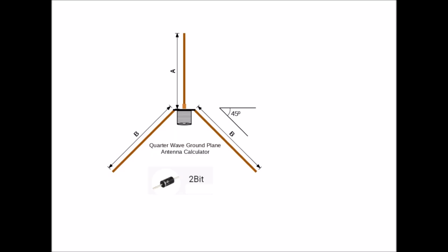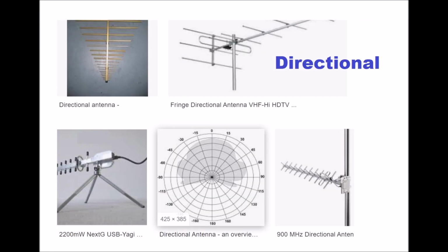Since monopole antennas rely on conductive surface, they may be mounted with a ground plane to approximate the effect of being mounted on the Earth's surface. More complex antennas increase the directivity of the antenna. Additional elements in the antenna structure, which need not be directly connected to the receiver or transmitter, increase its directionality.